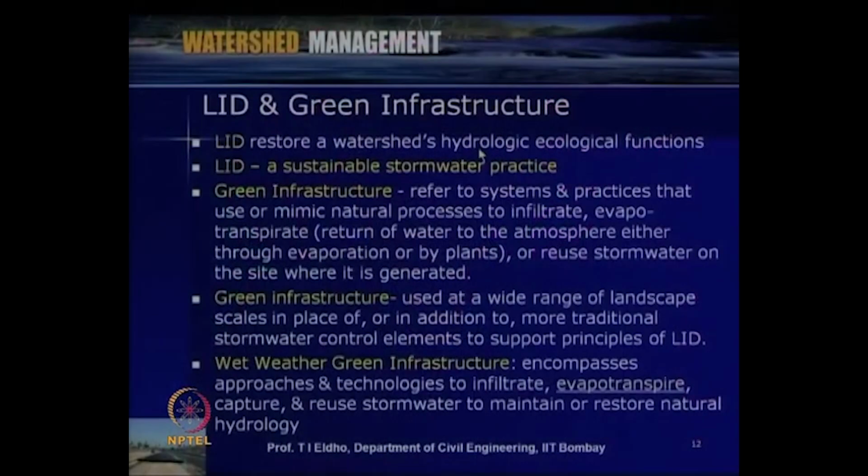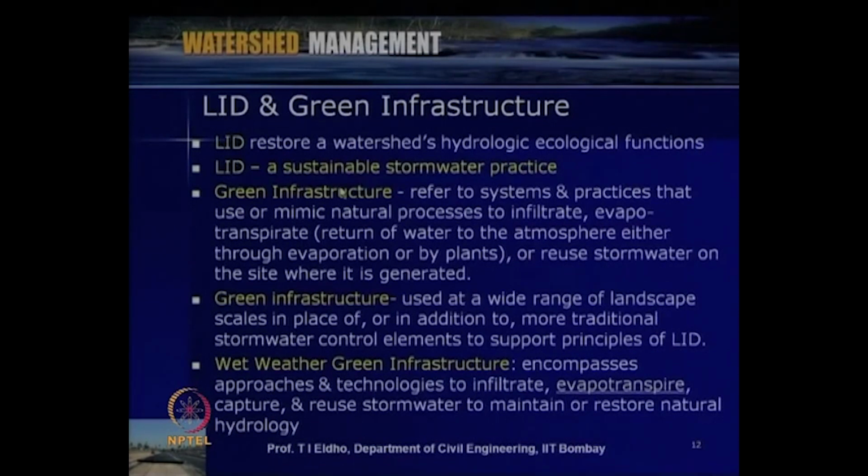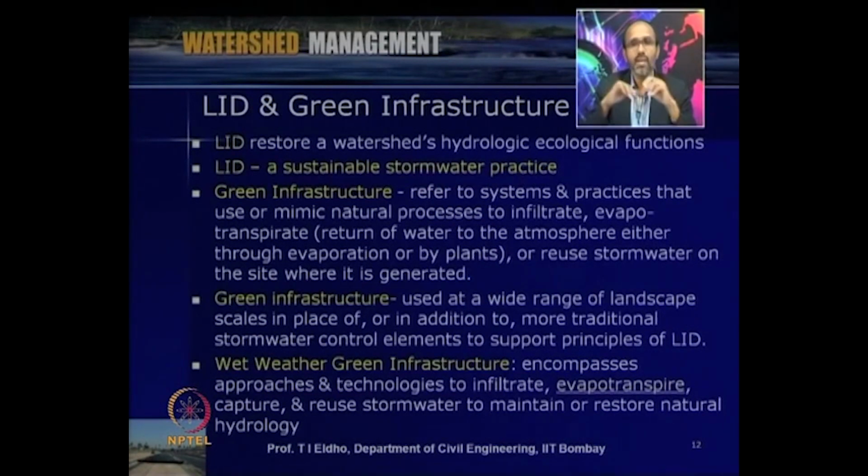And then another term as far as integrated stormwater management is concerned is green infrastructure. So, let us look into some more aspects of LID and green infrastructure. As I mentioned, LID restores a watershed's hydrological and ecological functions. As we discussed, LID is a sustainable stormwater practice. So, that way the sustainability issues are addressed, and the water will be kept within the watershed, and environmental improvement is also taking place.